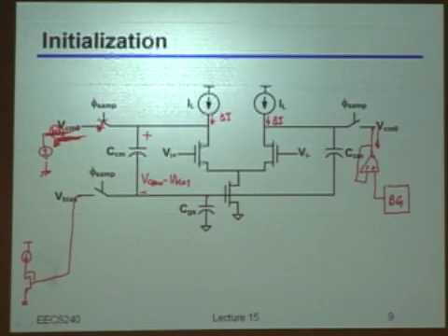So what happens is that if for any reason you had one situation in which VO plus was at this place and VO minus was at this place before resetting the amplifier, before resetting the common mode, and let's assume, for instance, that the common mode was a little bit off for some reasons, then after that, you will restore it, right? And then you have kind of glitches at the common mode level, so you will have big jumps in a small time, right? So you don't want this kind of behavior.